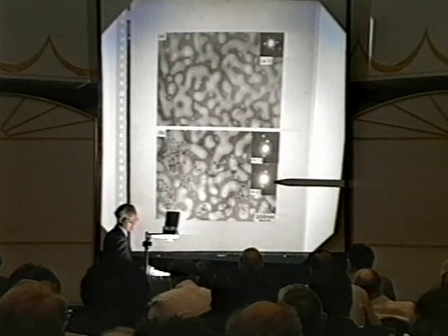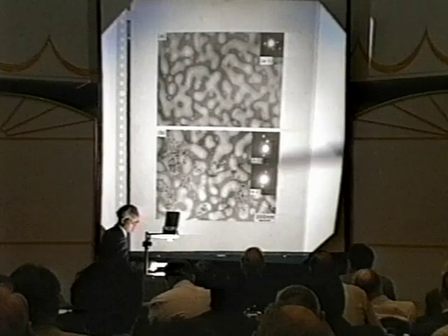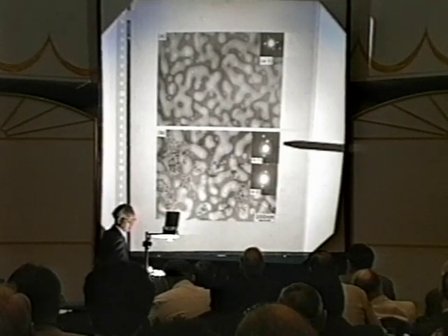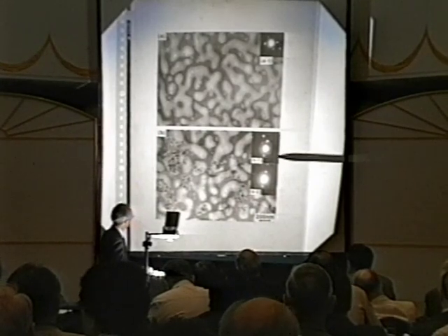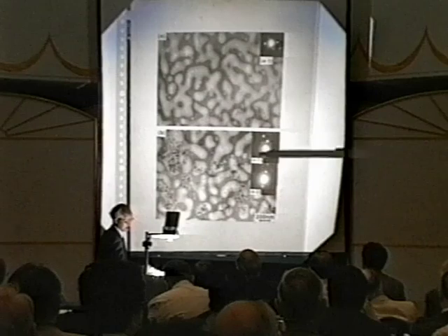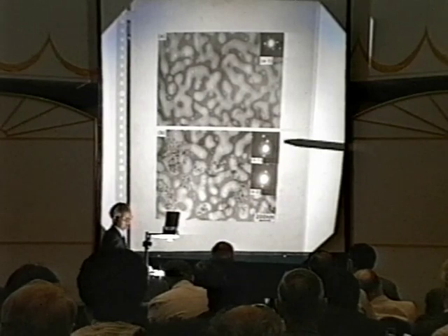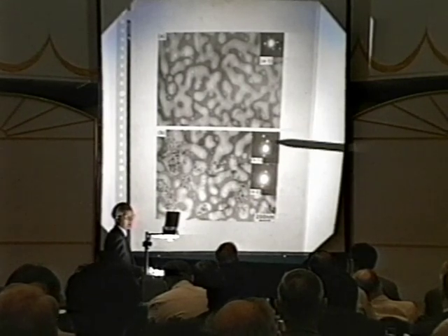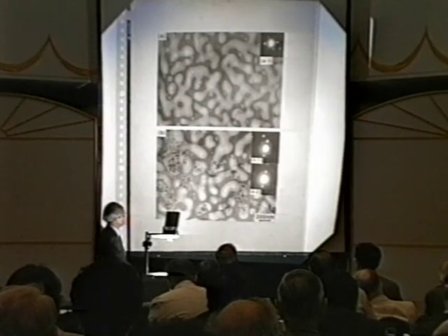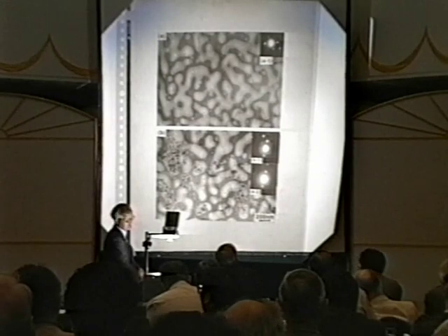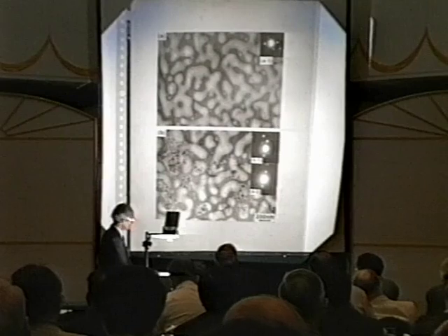When we take the diffraction around these regions, excluding the speckled regions, but including speckled regions, we observe these circular spotty rings. It reflects the presence of a polycrystalline part. So it means these speckled regions changed from single crystalline to polycrystalline structure.